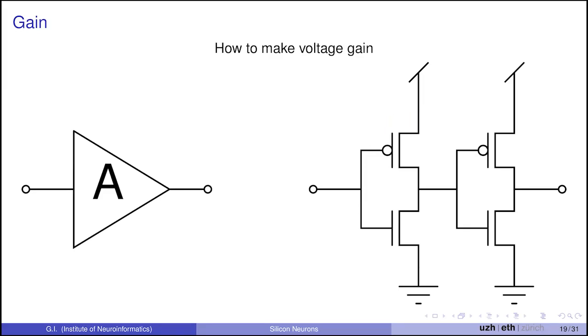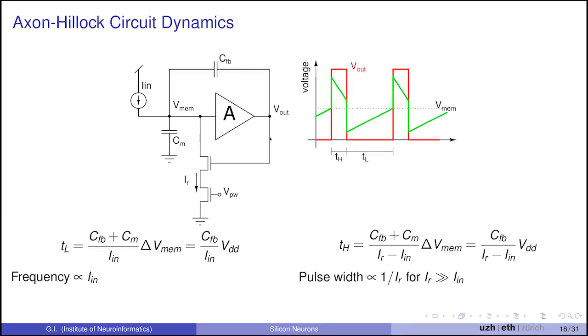If you think of it, you have input currents that are very small. We want to have biologically realistic dynamics. And so these voltages here are increasing over tens of milliseconds. And so when you reach the spiking threshold, the inverter's inverting threshold, you will be hovering around this threshold for some fractions of milliseconds.